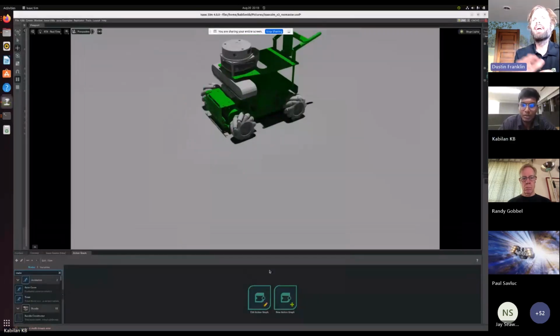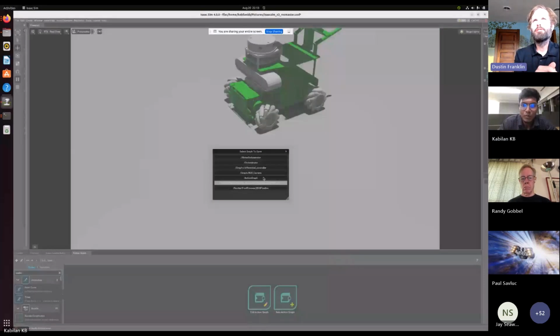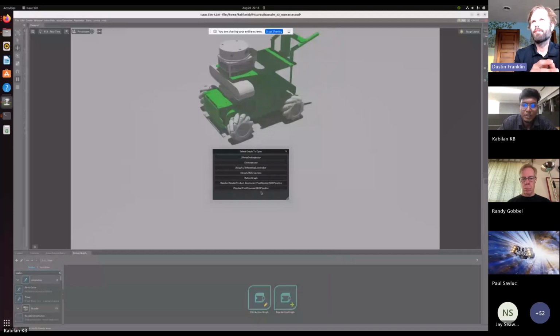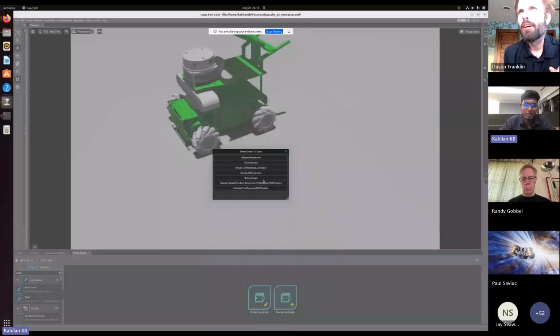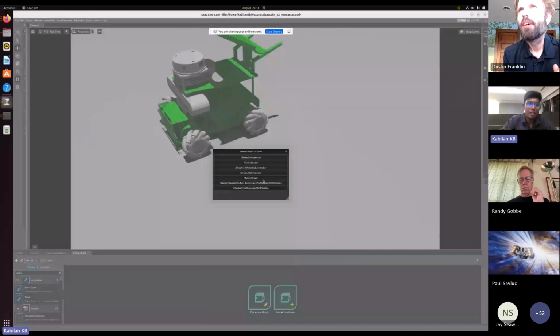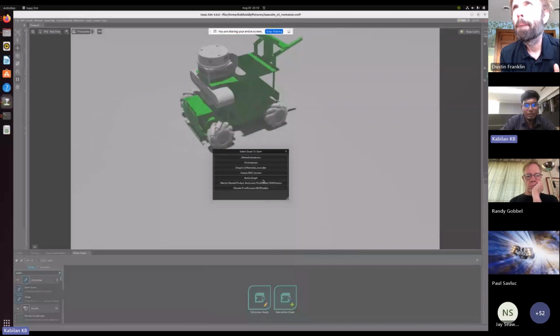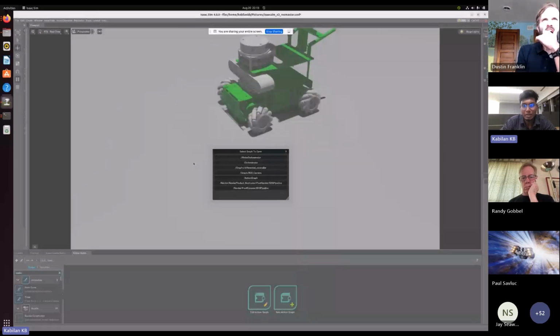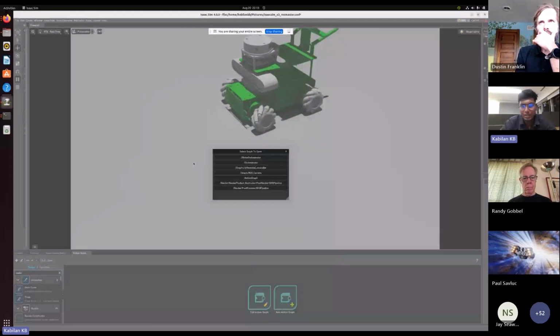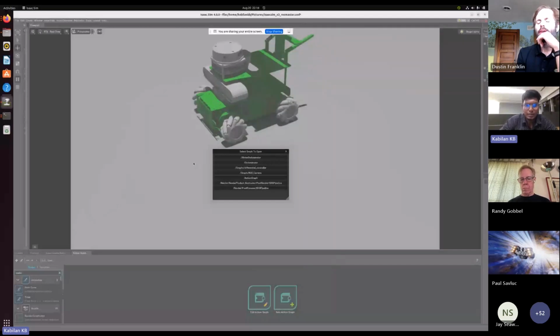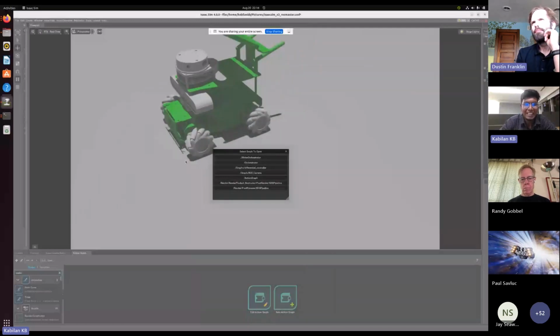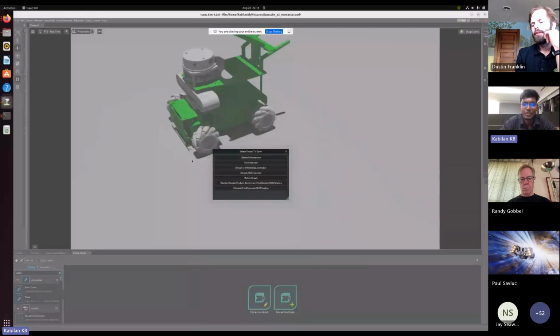Yeah, actually we can do the gain tuning point of view and PID tuning. Okay, what did you design this little robot in? Did you design it right here in Omniverse, or did this come from AutoCAD and was imported? Fusion 360, we need to design it first. We need to follow certain steps to create joints and links, and then we have a URDF converter plugin for Fusion 360. We need to convert it to the ROS 2 URDF format. So it will be created with a launch file script for Gazebo. If you are going to use Gazebo, it will create a Gazebo launch file and the RViz launch file, and other parameters and xacro files will be automatically created by a single click in Fusion 360 while enabling the URDF plugin.